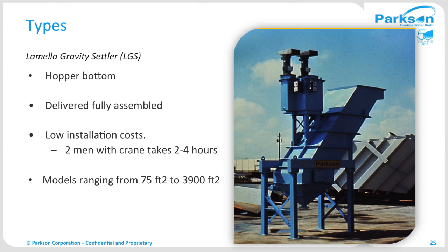Low installation costs compared to conventional clarification. It only requires 2 men with a crane. 2 to 4 hours for smaller units. For bigger units with assembly and installation, it probably would take 6 to 8 hours. And our models range from 75 square foot to 3,900 square foot.